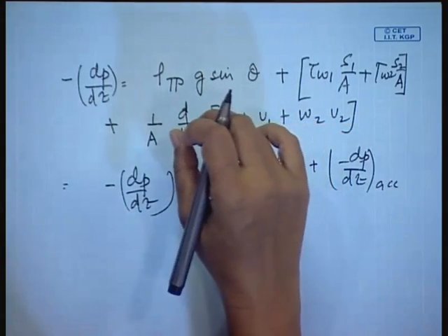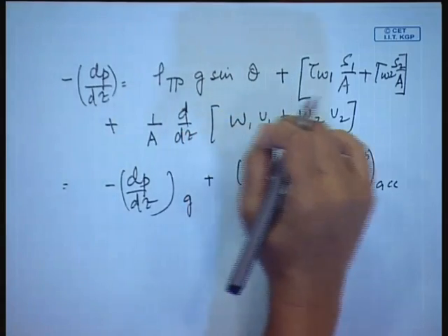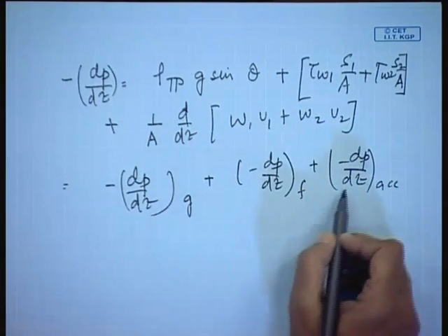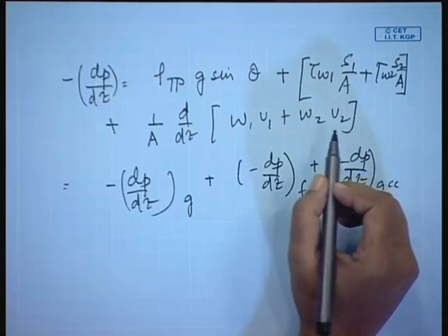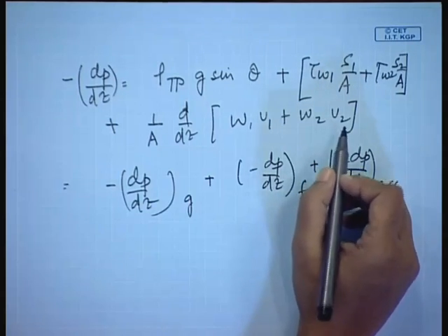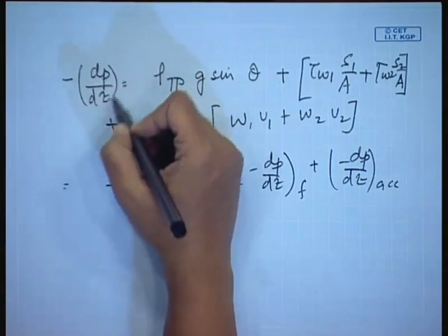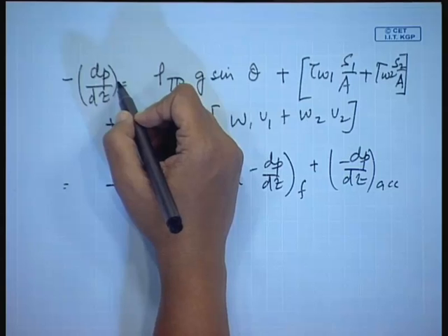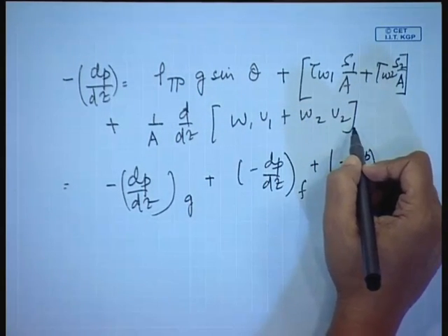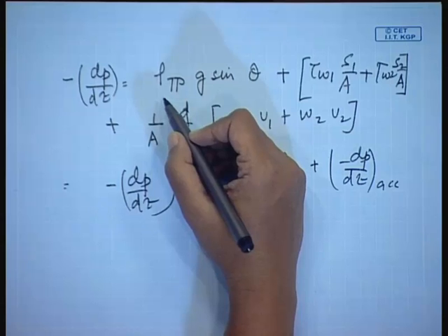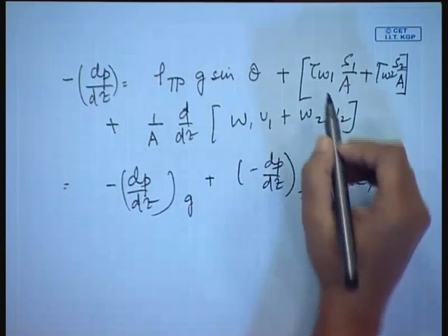We found out that for the homogeneous flow model, what we did, we expanded the acceleration pressure gradient. Why? Suppose we would like to find an expression for the pressure gradient or the pressure drop term from the equation which we have derived. We find rho TP; if we know alpha, we can find it out, isn't it?